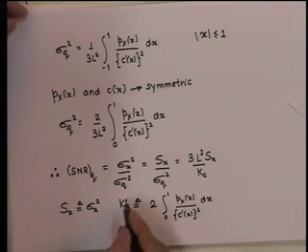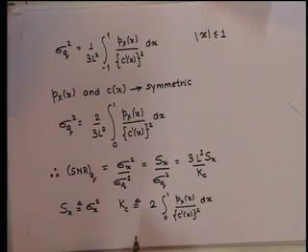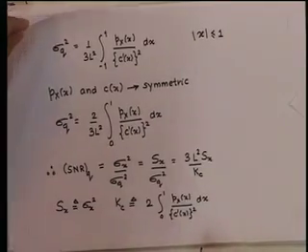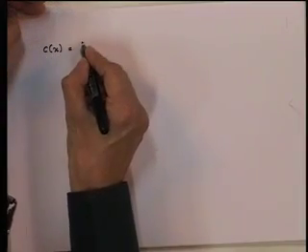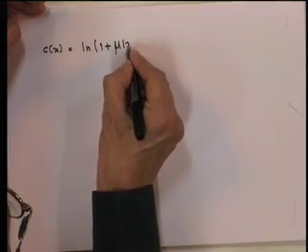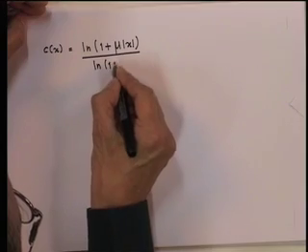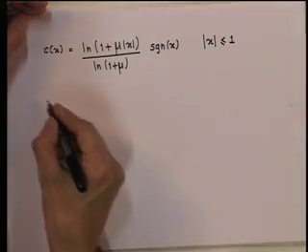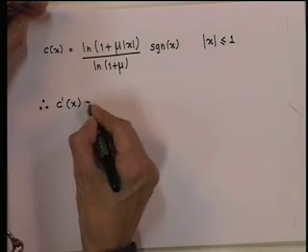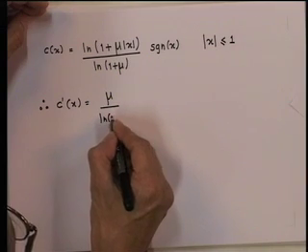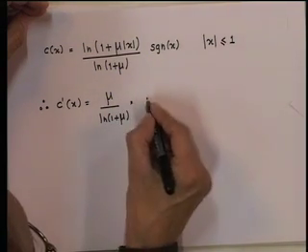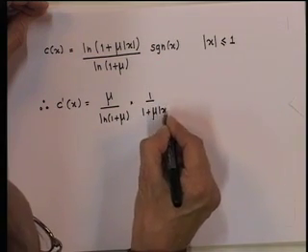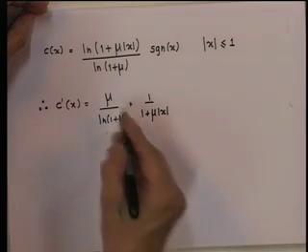So, this is a constant which is dependent on the compressor characteristic and the input PDF. So, in this case the popular mu law companding for voice telephone employs the following compressor characteristic. And therefore, c dash x is equal to mu by log 1 plus mu times 1 by 1 plus mu times mod x. The parameter mu is a large number.